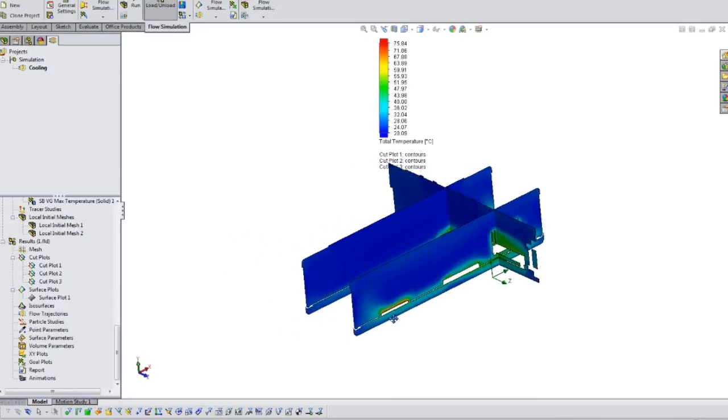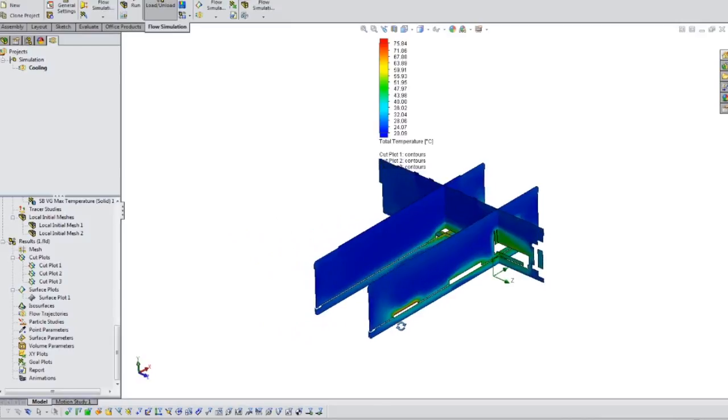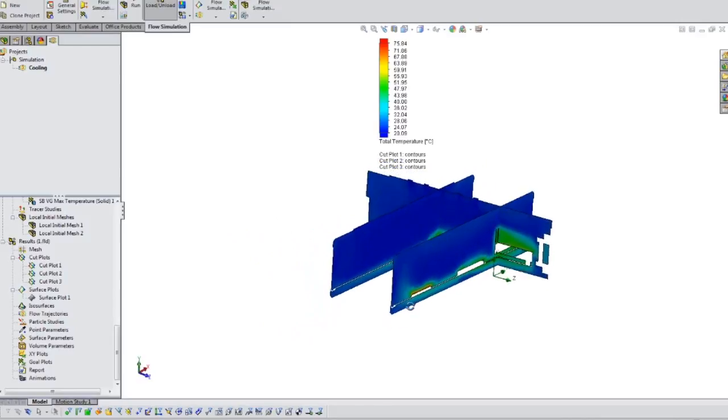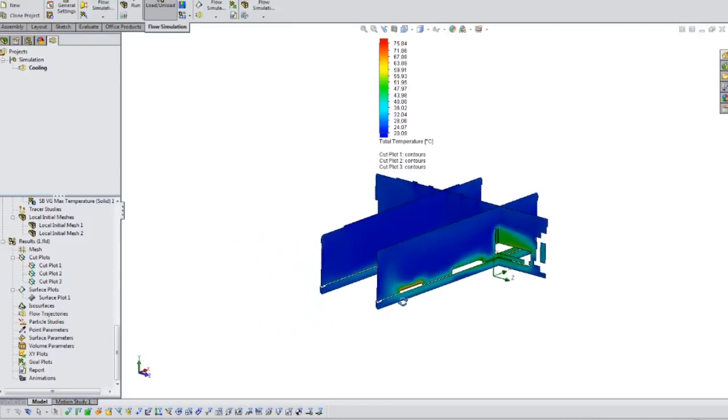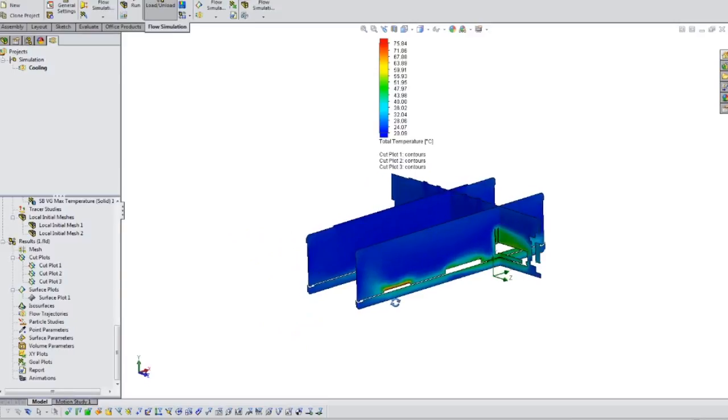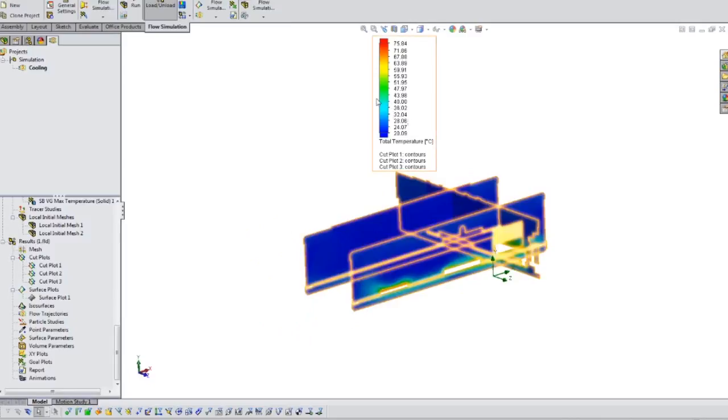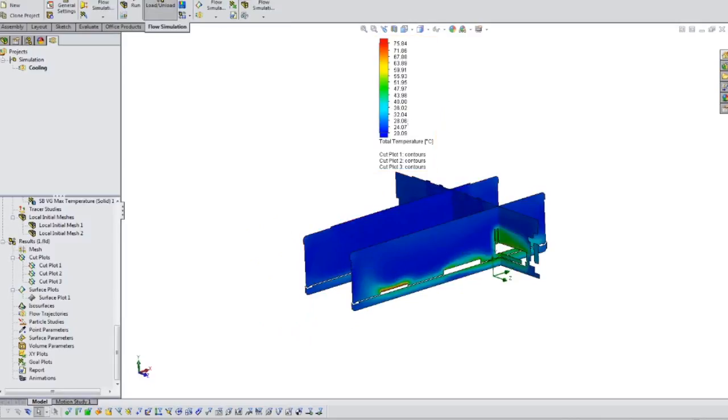We then tell the software, how does the flow get in and out of our problem? In this case, we have environmental boundary conditions on all the faces that we've blocked off inside of our model. And then to get flow into our model, we've actually created an internal fan. Again, this pulls from the engineering database. We just go in here, we can pull any of the fans, and it's just a curve of how the fan performs based on the pressure drop across its two faces.